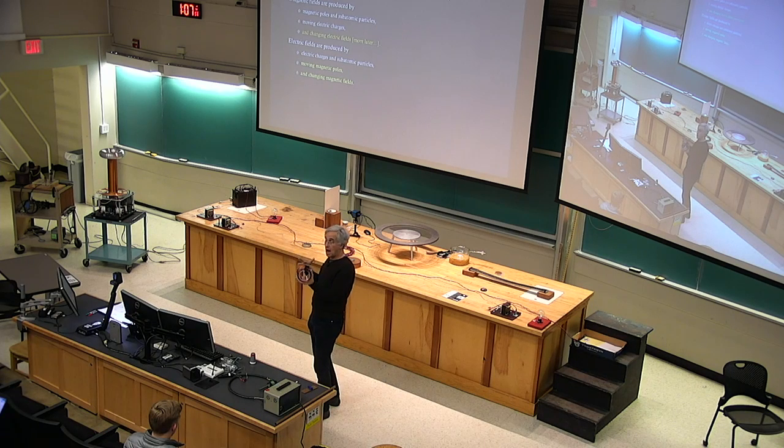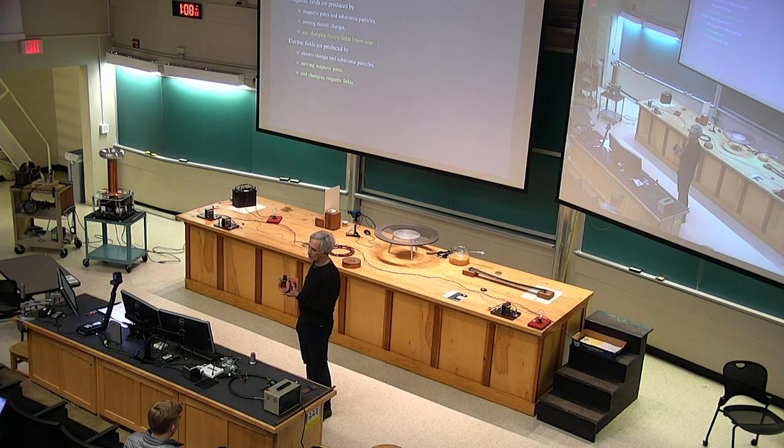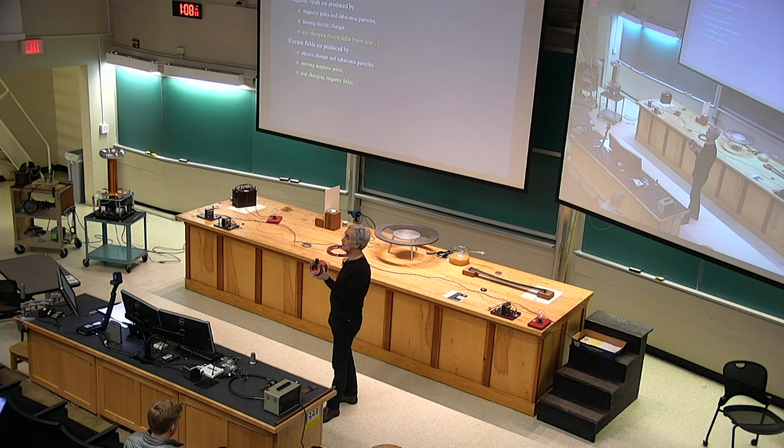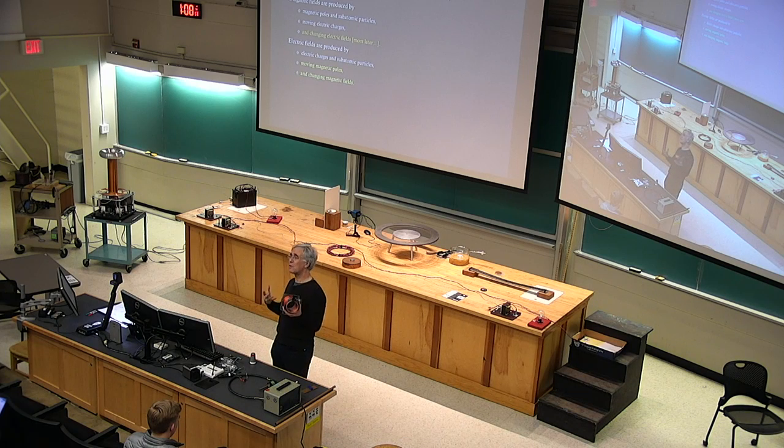Which means that there's no obvious source of electric power in this. What's ever going to light up the light-emitting diodes? The light-emitting diodes are arranged so that they light up when current flows. The green one lights up when the current flows one way around that loop, and the red one lights up when the current flows the other way around that loop. The name diode refers to an electronic component that handles current only one way. It's a one-way gate for current. So these guys, light-emitting diodes, like all diodes, only conduct electricity one direction. And we'll get the green one in one case and the red one in the other. So far, so good? How am I ever going to get current to flow in this coil of wire?